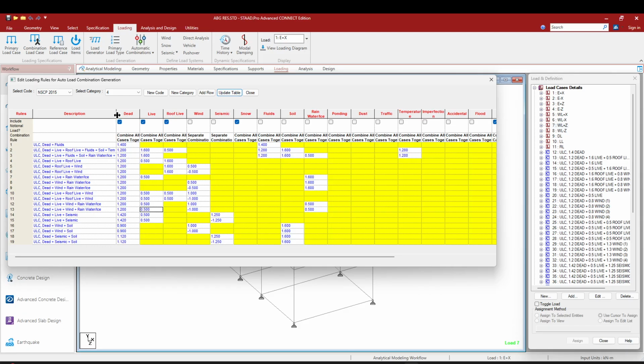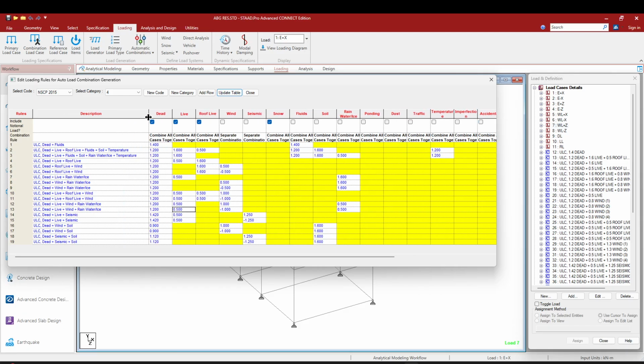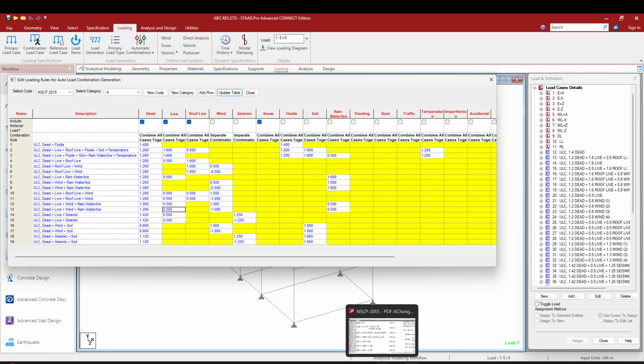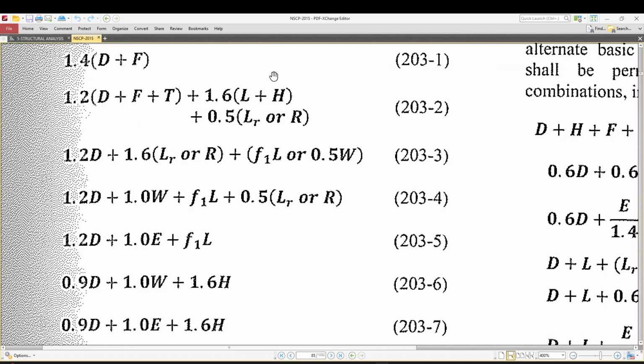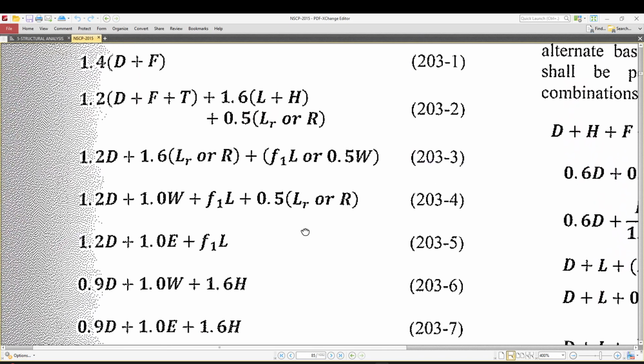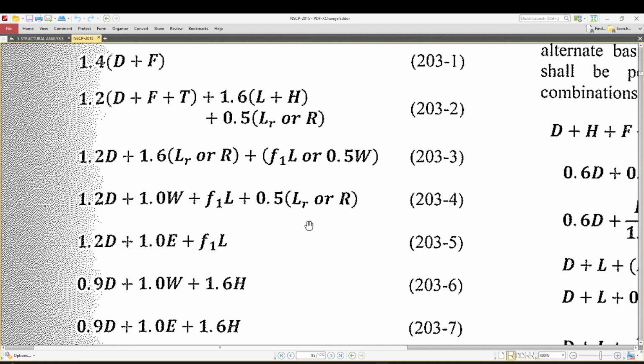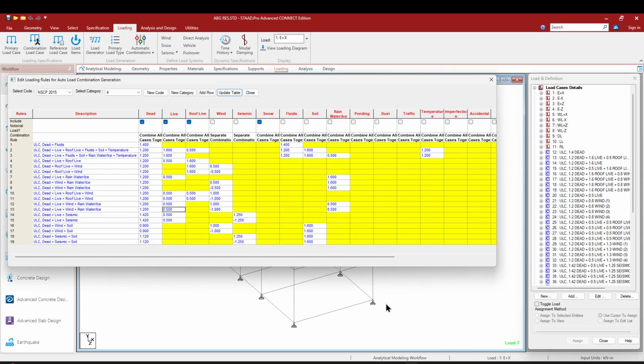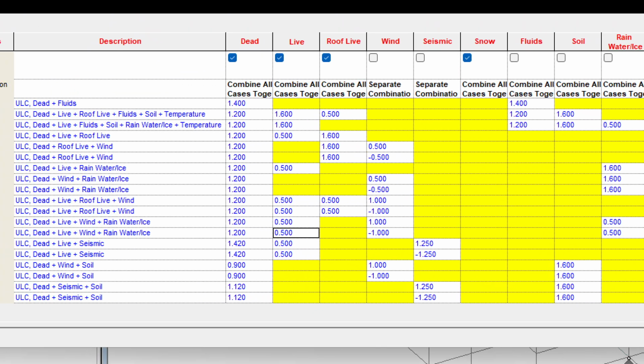So you might want to check or double check all of these loading combinations, if all of these loading combinations include our target combinations of these rules. Originally we have 7, but if we include the load reversals, meaning the negative, we just input that again, but with a negative sign for all the loading combinations which involves lateral loads such as wind and seismic or earthquake loads.